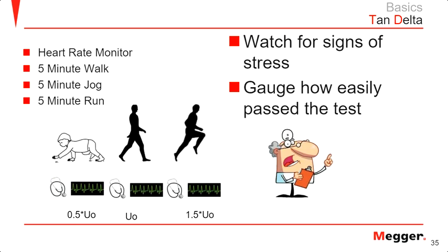Now, about the PD test, the way a PD test works is you get some reflected pulses back and that tells the partial discharge coupler, hey, this is coming from 500 feet of distance. If you have three phases hooked up at the same time, you will never know where exactly that partial discharge is coming from.